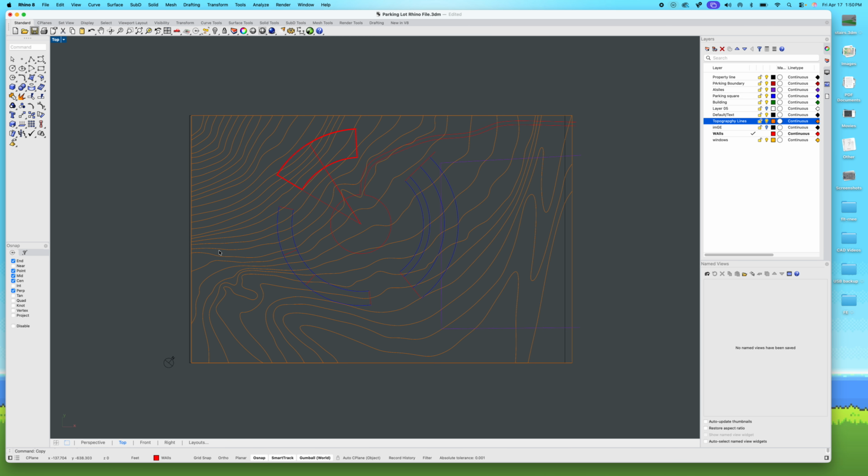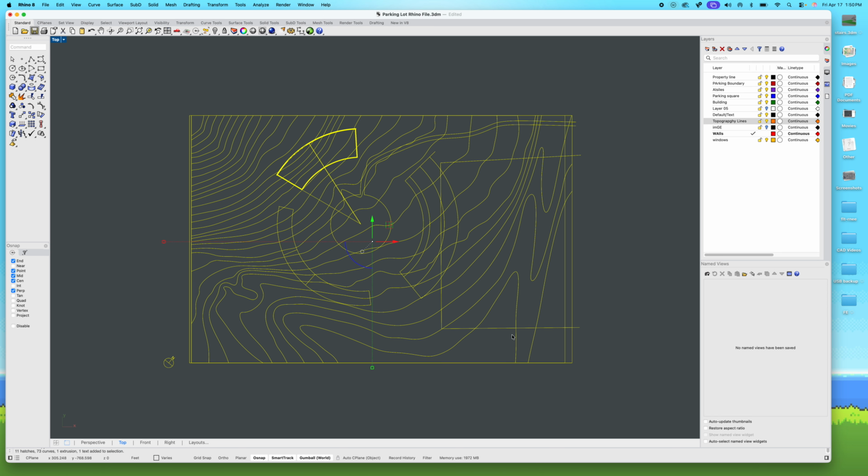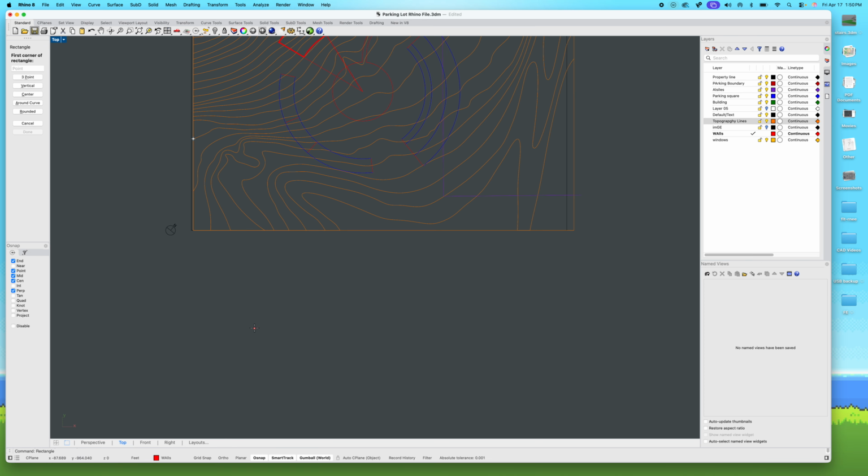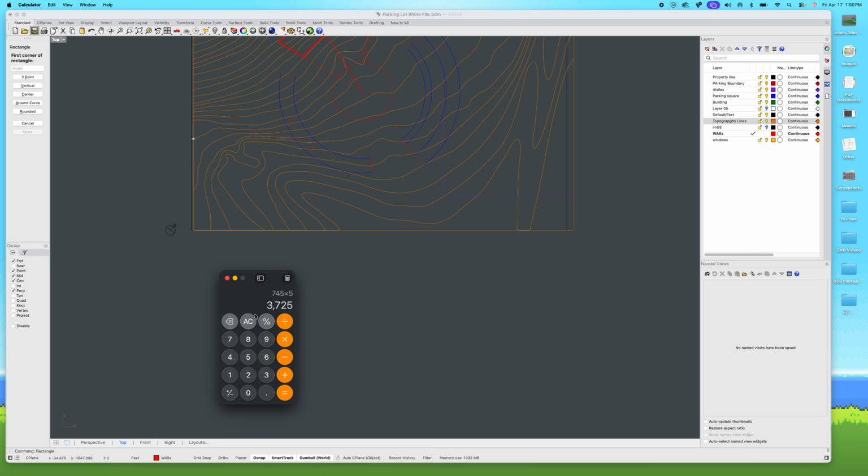But let's say I actually want to turn it into a line drawing for that Wednesday pinup next week. Let's do it. And what scale do we need it? 1/32? Let's do it, right? So we have to do a little bit of calculation. I just need to know my paper size, and I already expressed how big it was. So I'll pull up my calculator, and in my case, 1/32 means I can fit 32 feet per inch. Well, that's great, because if I have an 18 by 24, I already know how many feet I could possibly put on a piece of paper, no?